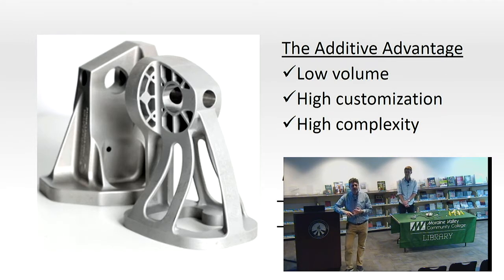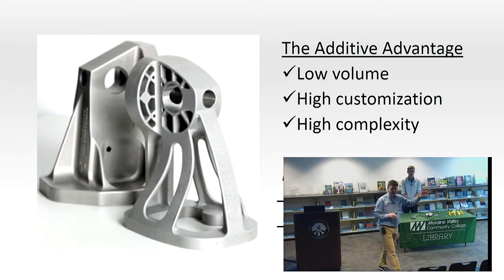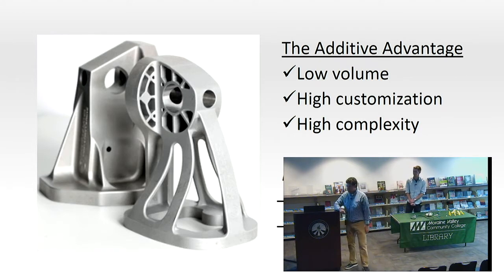The second thing is there's often, especially in the case of metal 3D printing, there is often post-processing that needs to be done. So the part has to be sintered to make sure it has full density. The part may have to be heat treated. Those are going to add hours or days to the process. So it's not just a one and done, hey, let's print it and move on. You know, there's hidden time scales in there that we have to be aware of.